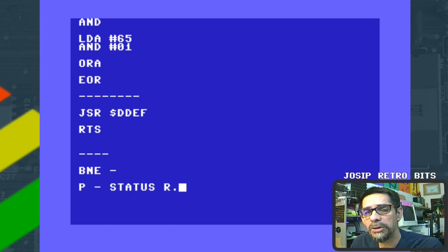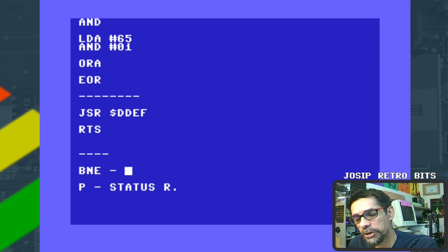And this status register has a couple of different, let's say, flags. One of those flags is a zero flag, then we have negative flag and some other type of flags which tell us if some value has reached 0 or something else. Branch if not equal instruction uses zero flag, which is just single bit in this status register.